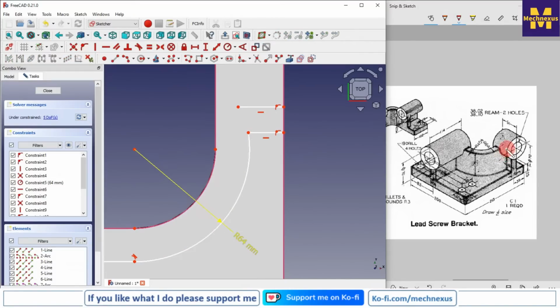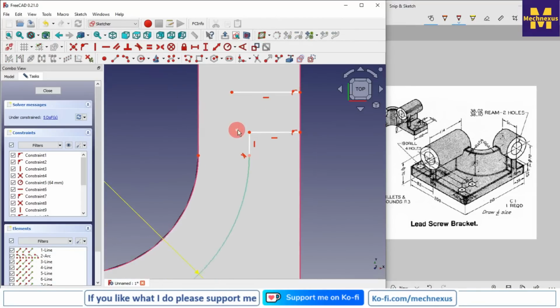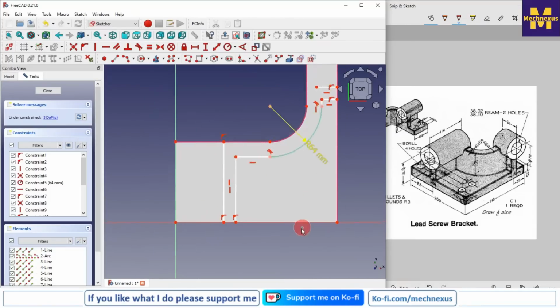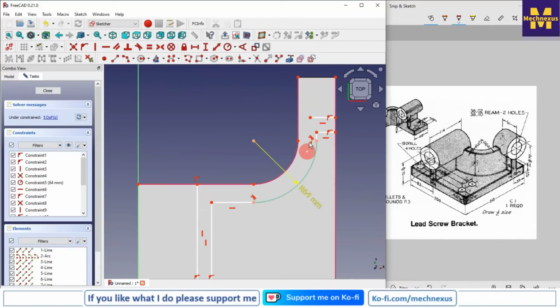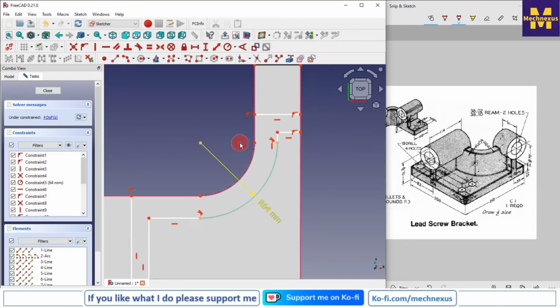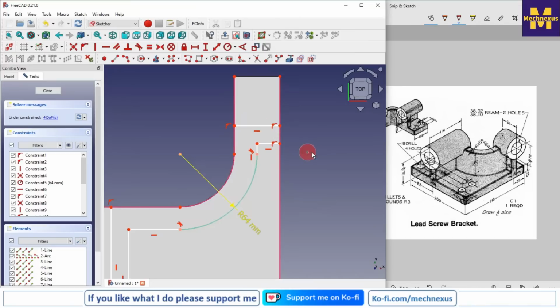So if you see here, there is also the tangency is required. So for this I will move my line like this and create a line and join it, and then I will add the tangency relation. Now we will give the dimensions, and before that we will add here the coincidence relation, and now we will give the position.